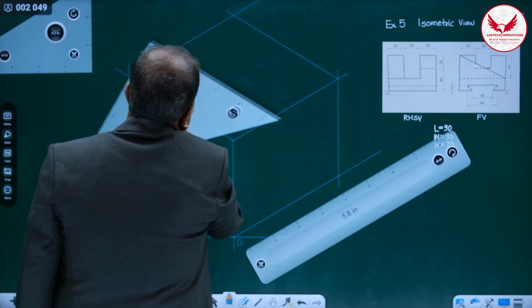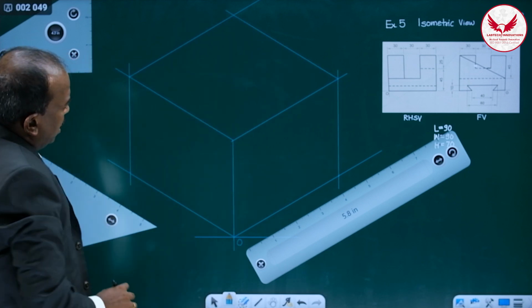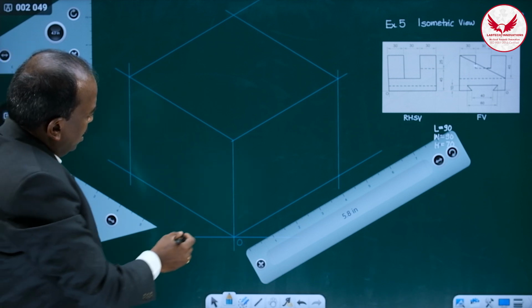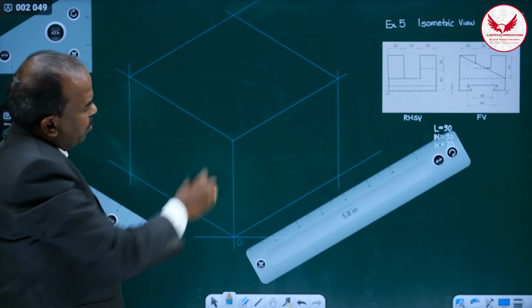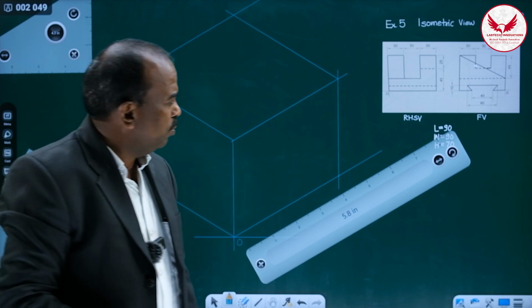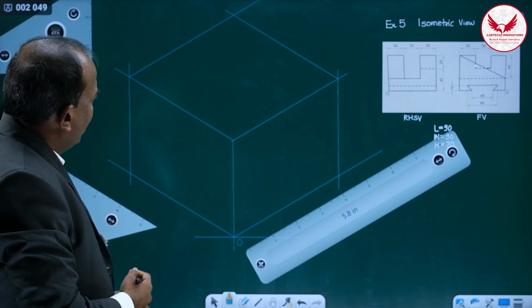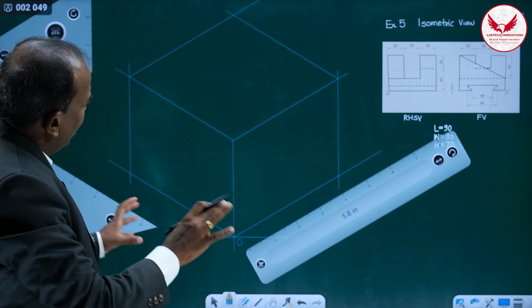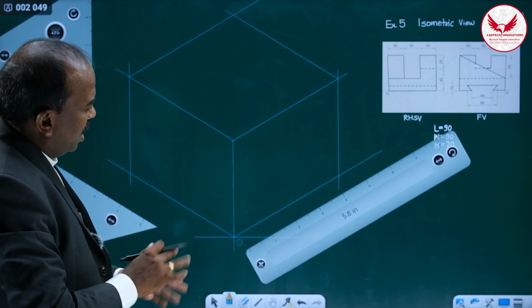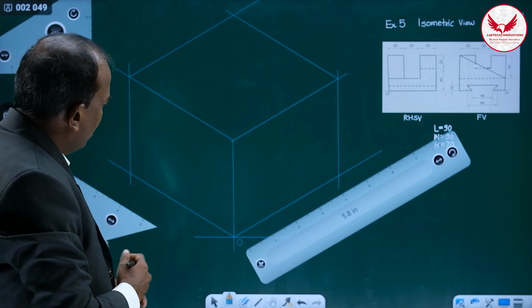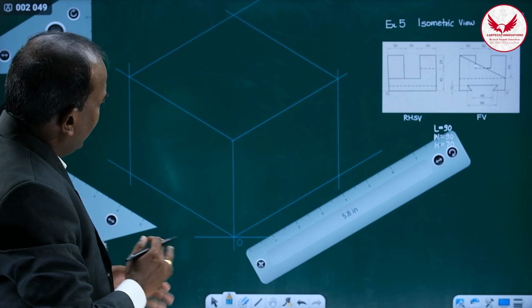It is the isometric box. While preparing the isometric box, always I suggest, once you mark the height, remove the upper portion. Then you will find the isometric box in an excellent way. These light lines you can draw more than required also. There will not be any problem because those are very, very light.